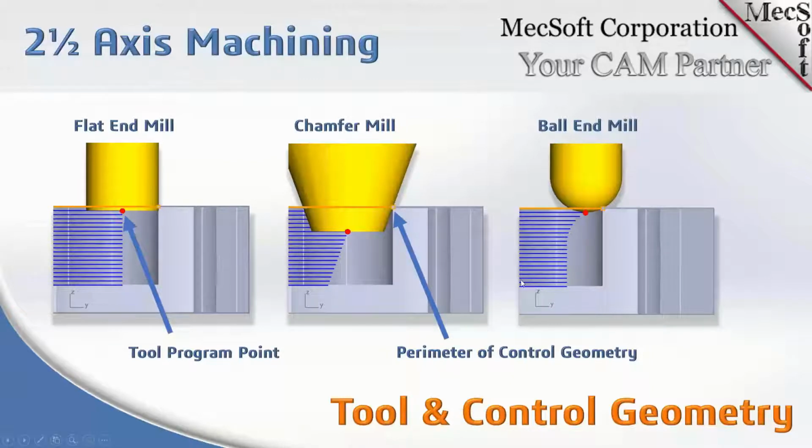So the deeper the taper tool goes down, the earlier it's going to stop. So you can see the red dot, and then it slants to the left all the way down. So at the bottom of the pocket, the center of the tool would be here. So you can use that obviously to cut chamfers. Also, you can use it to cut drafted walls. If you have a constant draft on a wall and you have a taper tool to match that angle, you can use that to machine that draft.